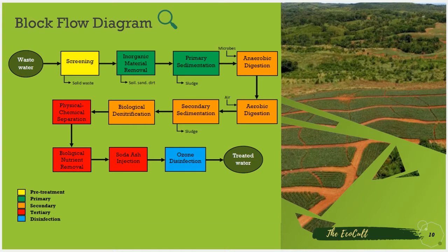The secondary treatment starts by putting the water in an activated sludge process to speed up the work of the bacteria in order to break down the organic matters such as sugar, proteins, and organic acids into harmless byproducts. After that, the water will proceed to anaerobic digestion, then biological denitrification to remove the chemical oxygen demand of liquid wastewater and anions respectively. Lastly, the tertiary treatment.